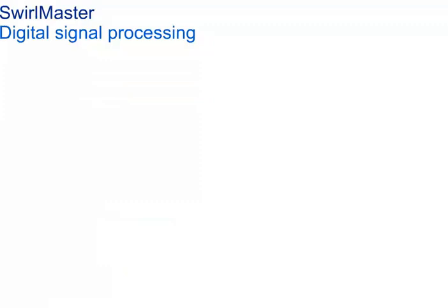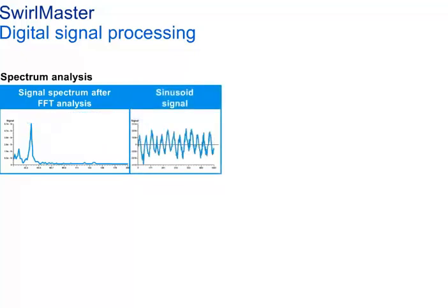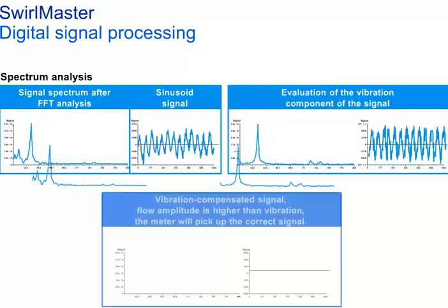The flow signal is often affected by hydraulic noise and vibrations, etc., which need to be filtered out for accurate and reliable flow measurement. Looking over the full spectrum of the frequency range, there are many peaks caused by noise or vibrations. Physically, all swirl flow meters generally measure in the same frequency range and have to overcome the same challenges. Only those with an intelligent signal processing combined with a sensor that provides reliable information can deliver the greatest performance under challenging process conditions.